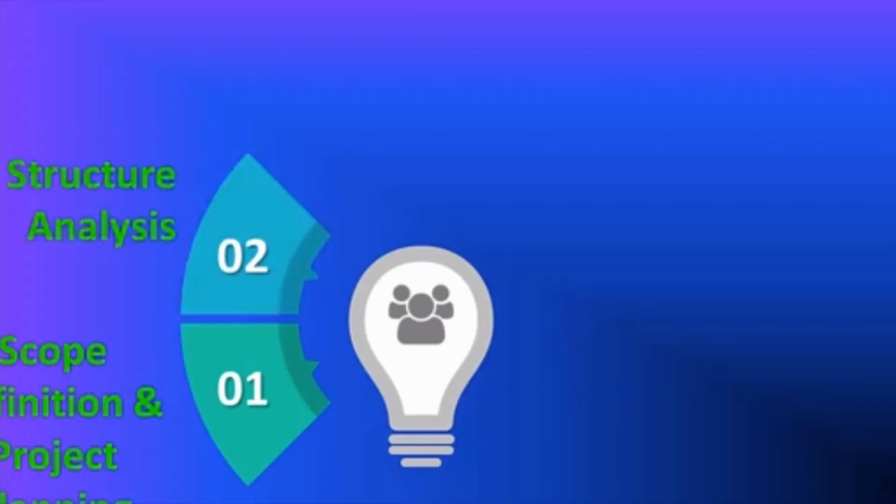The second part is structural analysis. Its purpose is to identify and break down the manufacturing system into 3 elements: process item, process steps, and process work element. Process item means what is the end result of all the successfully completed process steps. Process steps means the manufacturing operation under consideration. And process work elements, in this you identify potential causes with respect to men, machine, material, method, measurement, and work environment that could impact the process step.